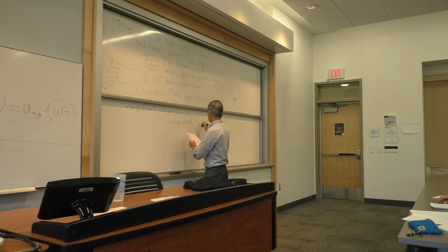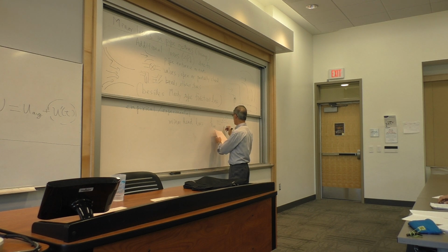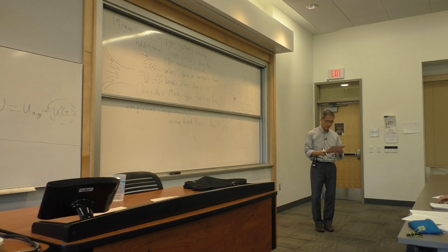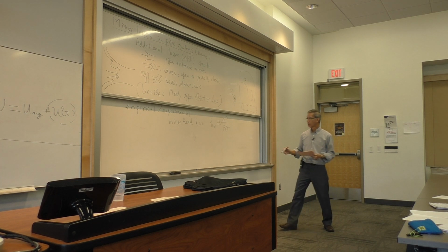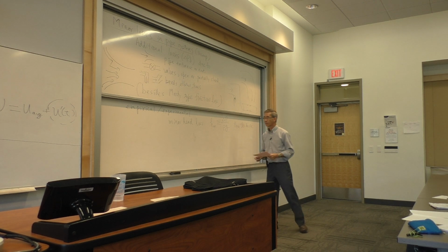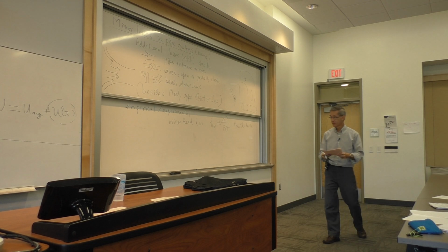And the way this is handled is to define a new term called minor head loss. That is different from the frictional loss that we have talked about. And the definition is, again, the equivalent head or length. And that delta P is the pressure drop through the device, which I can measure in my manufacturing plant for different types of valve, for different sizes.